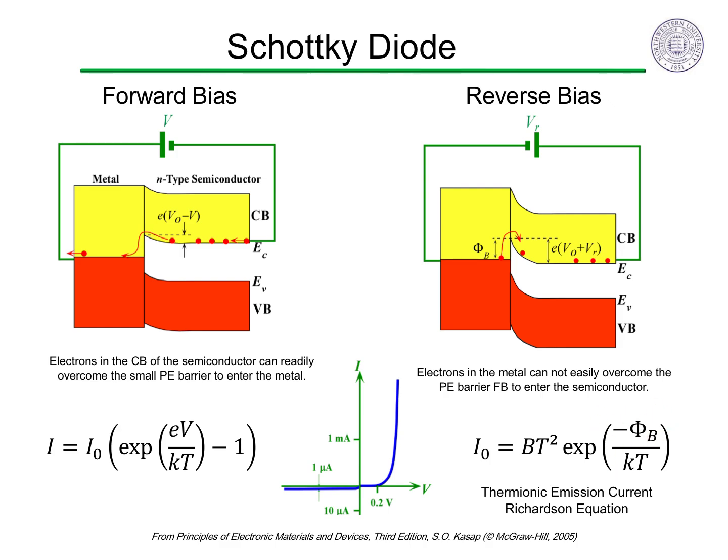P-type semiconductors also make Schottky junctions when there is a similar band offset with the valence band due to the Fermi level of the metal being higher than the valence band edge. While Schottky junctions can be used as diode devices, they are not great for simply contacting a semiconductor. They either limit the current or reduce the voltage, leading to a nonlinear IV characteristic very different from a normal resistor and are often called non-ohmic contacts.